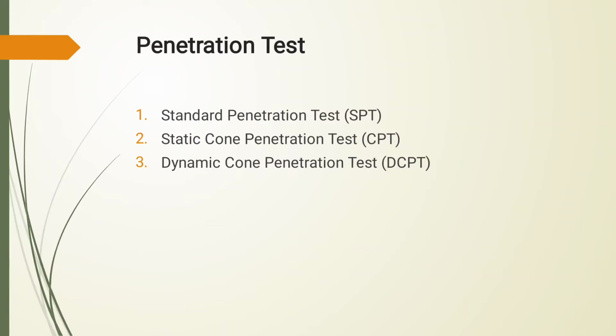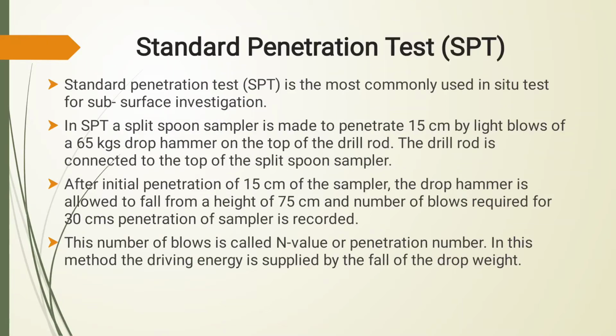First one, penetration test. The penetration test is conducted to measure the resistance of various soil strata. There are three types of tests: standard penetration test, static cone penetration test, and dynamic cone penetration test. First test is standard penetration test.